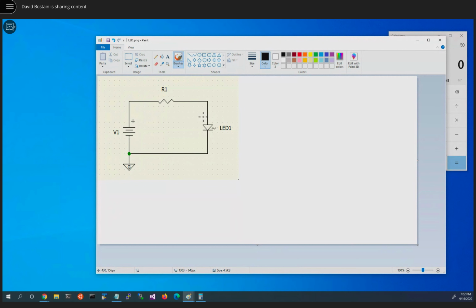Okay, so what we need to do is determine some things. For instance, we're designing the circuit. If I'm saying we're designing it, I can't give you a resistor value and know for sure we're going to be successful, because the resistor value might not allow the forward voltage to fall in the correct range. I might give you a problem like that sometime, and part of the solution would be, I have to get a different LED with different forward voltage characteristics, because I can't design one given that value. But I can give you different voltages here, and I can give you specs for this or not. If I don't give you specs, we make some assumptions.